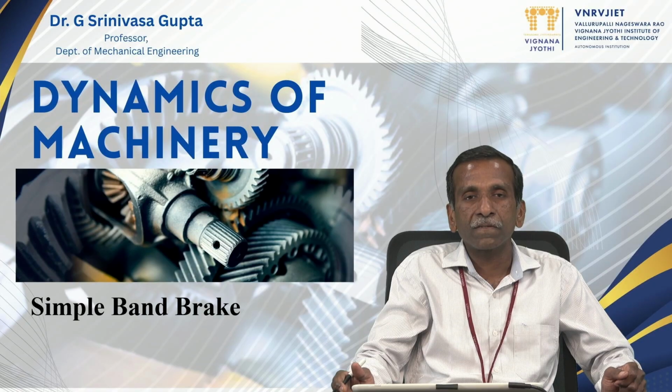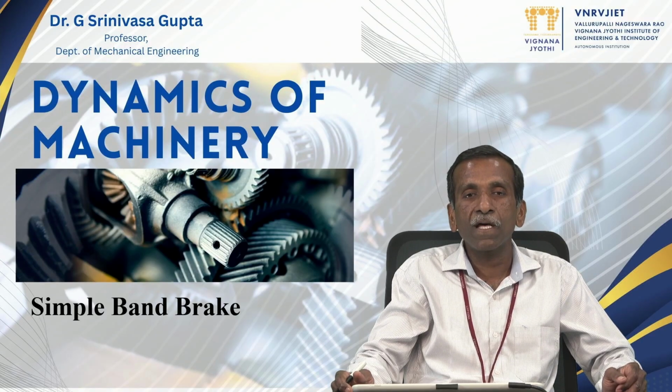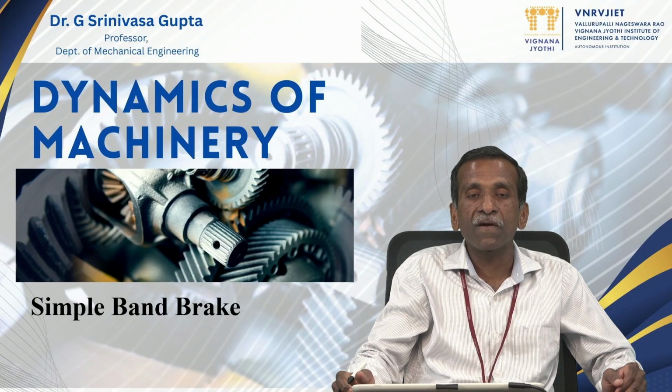We have seen the difference between shoe or block brake and pivoted block brake. In a shoe or block brake, the shoe or block is rigidly fixed to the lever that comes in contact with the rotating drum. Due to frictional resistance, the brake is activated. In a pivoted block brake, the block is not rigidly fixed to the pivot, and in that case the equivalent coefficient of friction is estimated using the relation mu dash equal to 4 mu sin theta by 2 theta plus sin 2 theta, that we need to use for our braking torque and frictional force